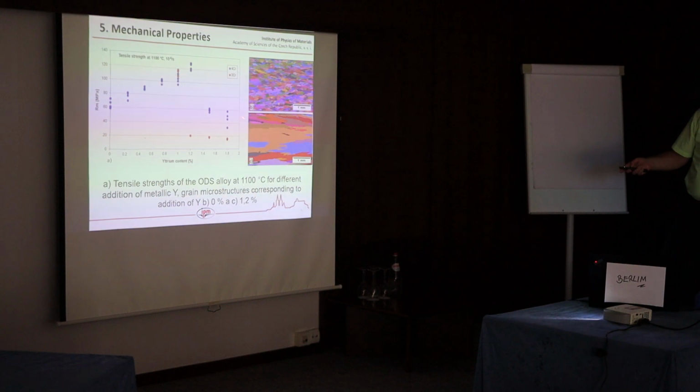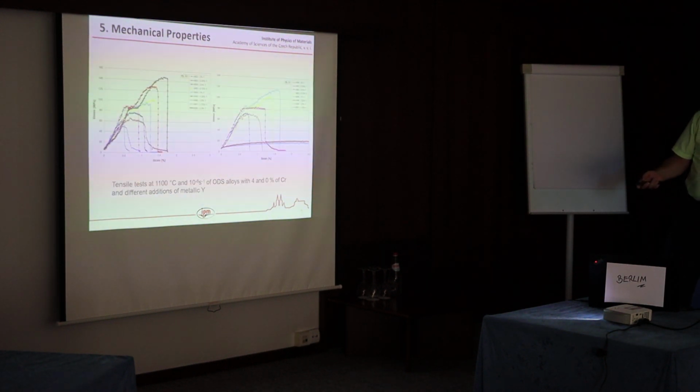It's only partially recrystallized, but this yttrium content and also chromium content have a very high effect on the size of the grains after the secondary recrystallization. And larger grains means better creep strength.